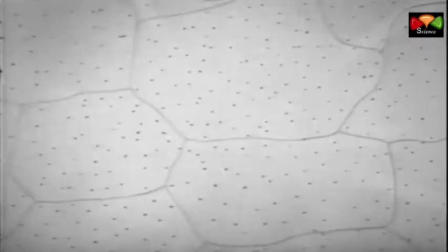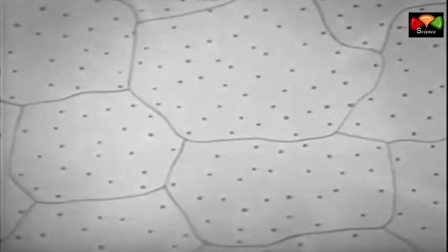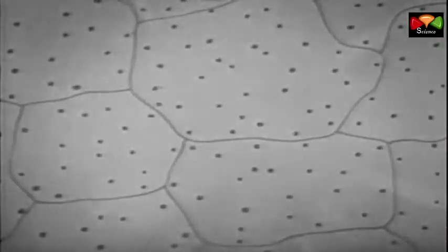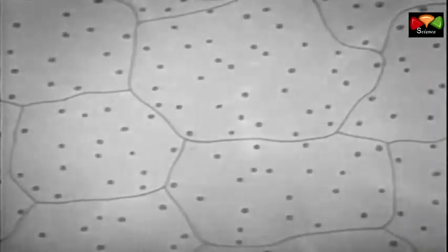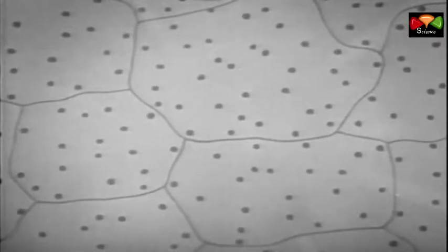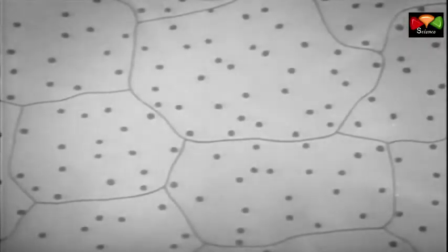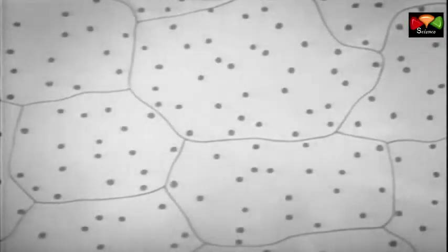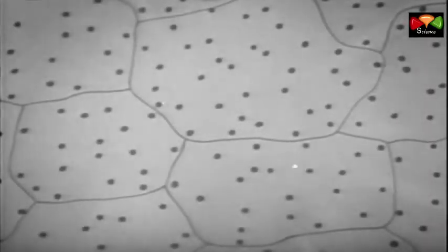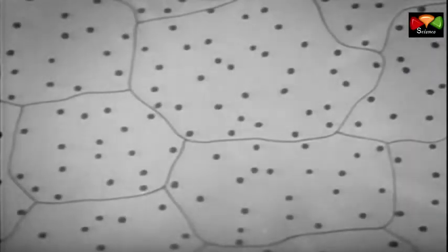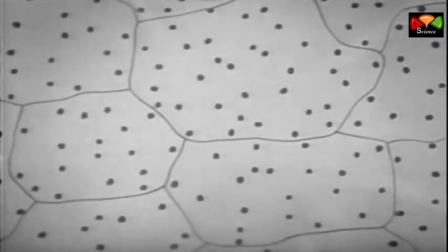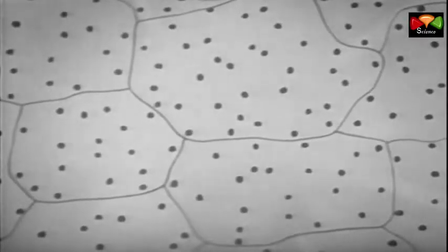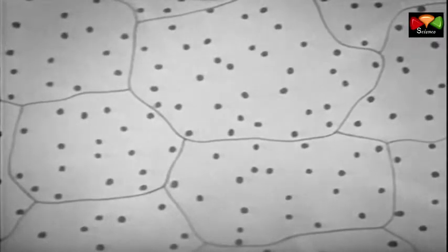In the annealing of a heat-treated alloy, the metal is heated at temperatures below the heat-treating range. The effect is to increase and accelerate the precipitation of this copper aluminum compound from solution in coarse particles. This reduces the strengthening effect of the previous heat treatment. The alloy is now in its annealed or soft condition.